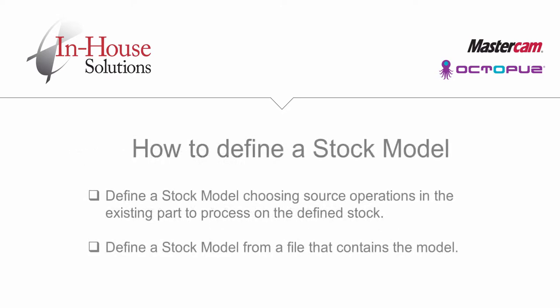Stock models are created in the Toolpaths Manager in the same way as you create toolpath operations. Being a toolpath operation, you can display the stock model or hide it using the same toggle toolpath display on selected operations icon. Most commonly, to define the stock model, you first set the original stock and then select the operations from which you are generating the stock model.